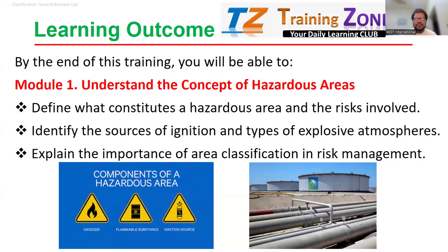So I hope you will remember that, because with any smallest ignition or even heat, sometimes a terrible explosion, a terrible kind of fire incident could happen. That's why we nominate them as zone 0.